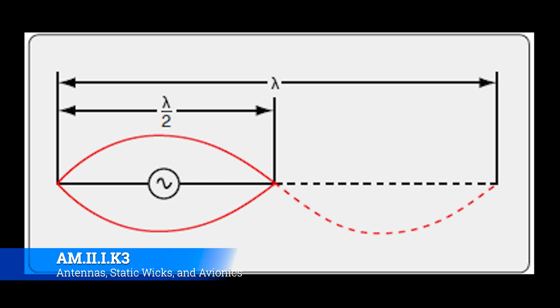The negative phase of the full AC sine wave is accommodated by the voltage and the current simply changing direction in the conductor. Thus, an applied AC frequency flows through its entire wavelength, first in one direction and then the other. This produces the strongest signal to be radiated by the transmitting antenna. It also facilitates the capture of the wave and the maximum induced voltage in the receiving antenna. All right, so that's a lot, but essentially what it means is that there's a precise length that is optimized for any one AC signal that will allow it to have the most bang for its buck.